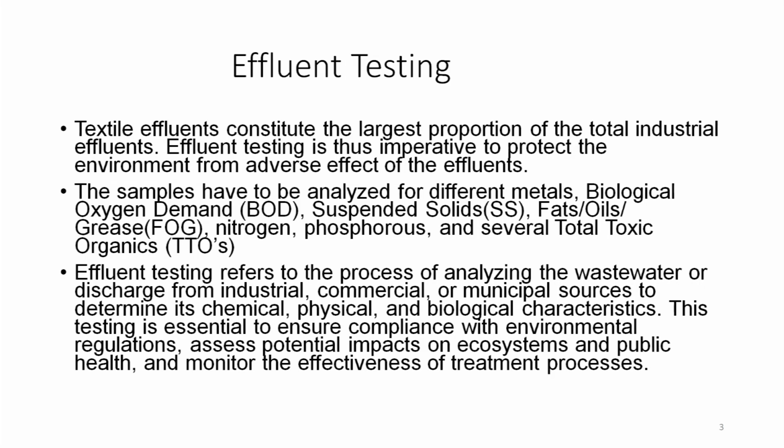The effluent testing refers to the process of analyzing the wastewater or discharge from the industrial, commercial, municipal sources to determine its chemical, physical and biological characteristics. This testing is essential to ensure compliance with the environmental regulation, assess potential impact on ecosystem and public health, and monitor the effectiveness of treatment processes.